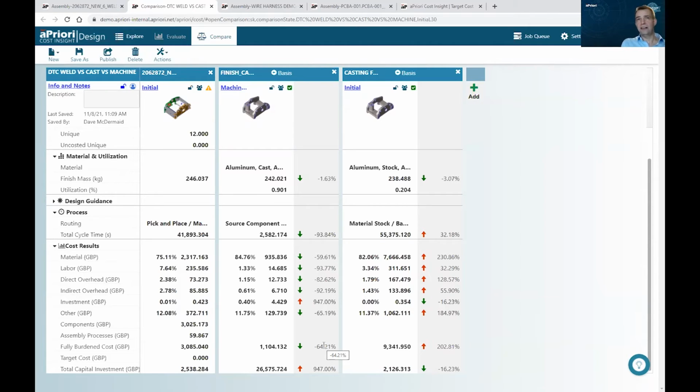What it can also tell us is that if we go down a casting route and casting becomes a risky process through supply chain because of pandemics and Brexits and things, then, well, I could machine from solid. That could be my get out of jail strategy. And the cost of machining that from solid is a lot higher, of course, but I can plug that into my risk equation. Fabrication is much easier to do and there's less risk around it, but it requires tooling and fixturing. I could go straight to manufacturing from solid if the world changes and have a supply shortage. It gives me options.